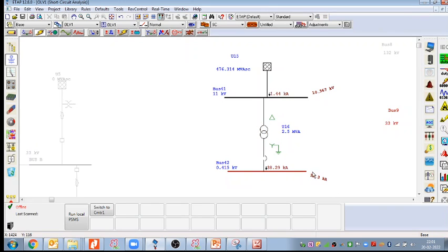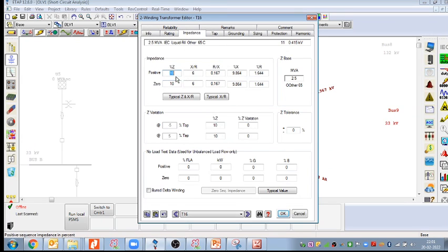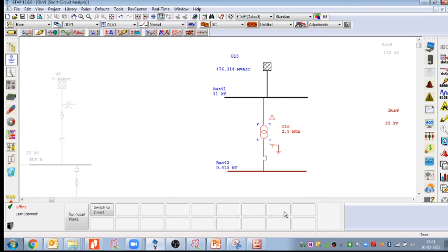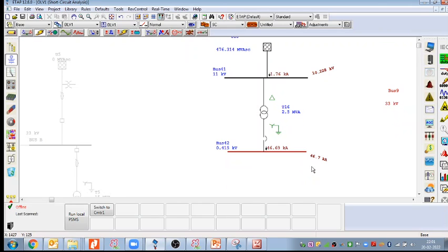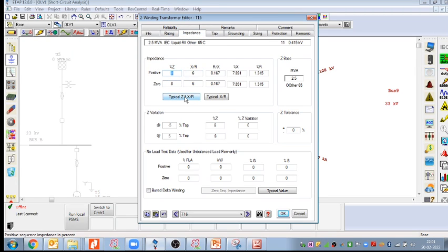Yeah, we can see 38.3, so that is very much less. So we can again go to 8, and click OK. It shows 46.7. Yeah, 46.7. The 50 kiloampere switchgear is easily available in the market right now. So I can play with this impedance, and in place of 6.25, the default impedance, I can go with the higher impedance rating, 8% impedance rating.